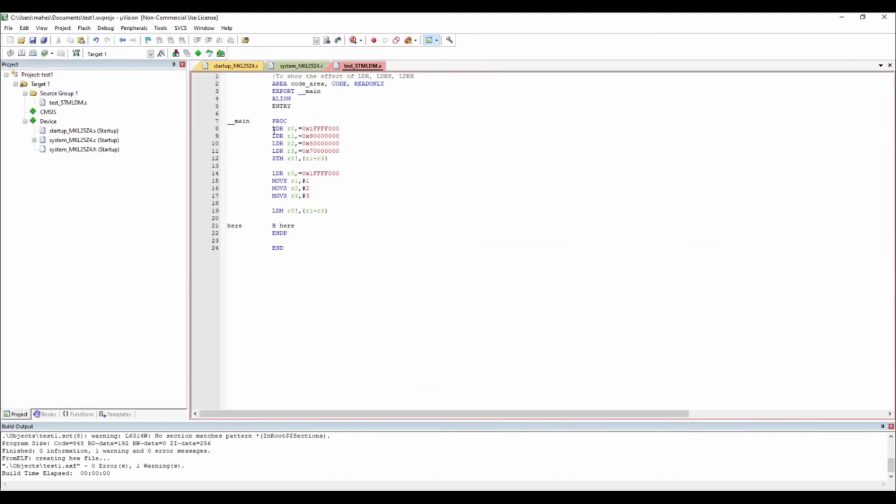Yeah, so this is a code. What we are going to do is, this is some address location which is read-writable for us. That is what is stored in R0, and then in R1, R2, R3 I am storing the values as in the slide. Then using this multiple store option, this address location is loaded with the contents in R1 to R3, and the content in R0 is also incremented. That is what this exclamation means.